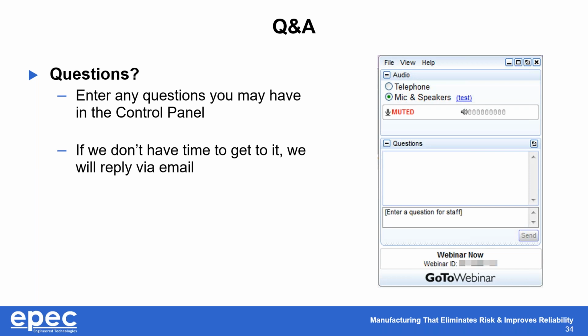Now, the real issue with this is that the way you measure this on a Class 3 or on a mil board is on the coupon, right? You're not going through and measuring every board to see if you have that amount of copper. And the problem is that the coupons are on the edges, right? So you want to make sure that those coupons come out good, because if the coupons come out good, the theory is the rest of the boards will come out fine. The challenge becomes that if the coupon's bad, basically the panel's bad. You can't say that, oh, the boards inside the panel are fine, just the coupon's bad. So that's why it takes longer, because we have to make sure that the coupons are good as well. So that's what adds some cost to Class 3 versus Class 2.